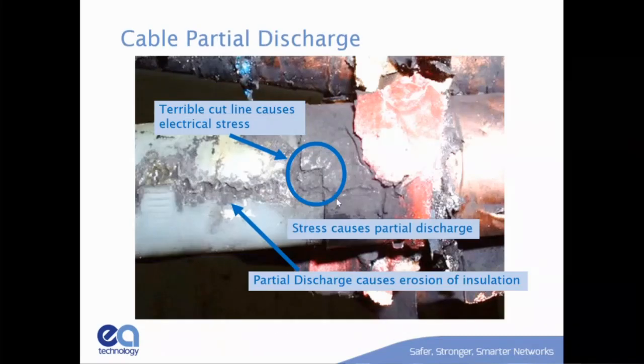Here's a classic example. I love this picture. My favorite picture out of all of them. If you're cable joiners at all, and you see this semicon layer, and you see this cutback, you guys having a bad day. This sharp corner caused a concentration of electric field. That caused discharge. The discharge traveled up the XLPE, ate through it. You can see where it's actually eaten through. That's from the heat of the spark eating through it. Also, notice that this is carbonized. It leaves a carbon track so that I now have the effect of voltage in places that I didn't plan.